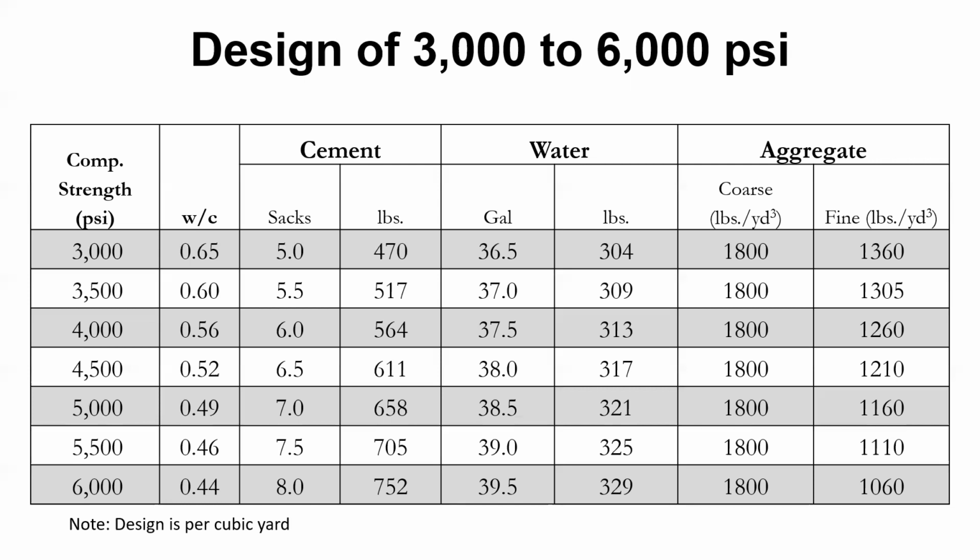And then maybe when you get to 4,000, maybe you add a much higher amount. Maybe you add 8, 9 ounces to still reduce the amount of water, so you can still have this water cement ratio, but you're still at maybe 5 sacks. Does that make sense?